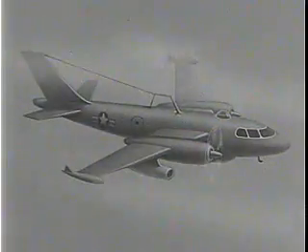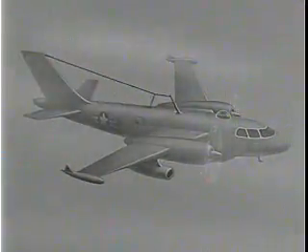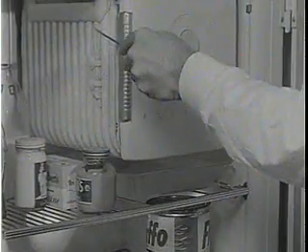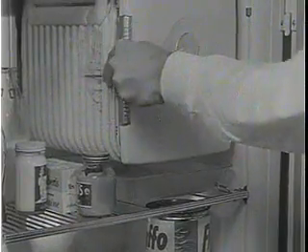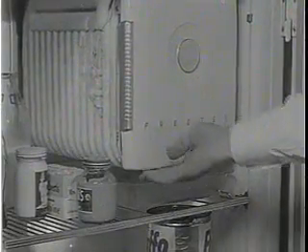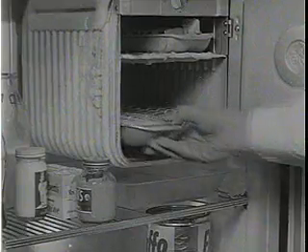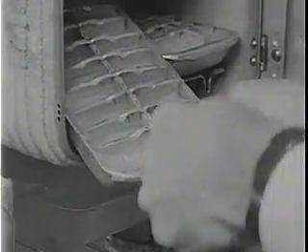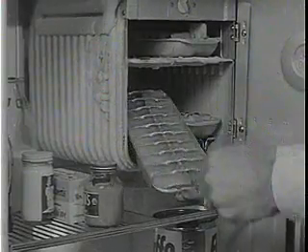We may find the two types of ice normally encountered in the structural icing of aircraft in an ordinary household refrigerator. The white granular ice that forms on the freezing compartment is rime ice. It is not very cohesive and can be flaked off easily. The hard, glassy ice in the trays is clear ice. This type of ice is very cohesive and is difficult to break loose.